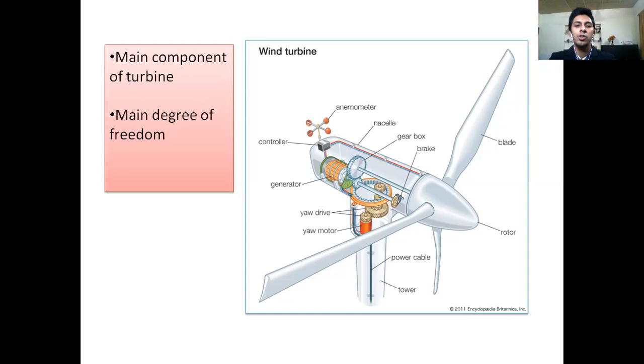The blades rotate in a vertical plane. Where the shaft is vertical, it is called a vertical axis wind turbine, also driven by lift. Another typical vertical axis turbine is the drag-based turbine, where the drag on one side is larger than the drag on the other side, and therefore that creates a moment that makes the shaft rotate.